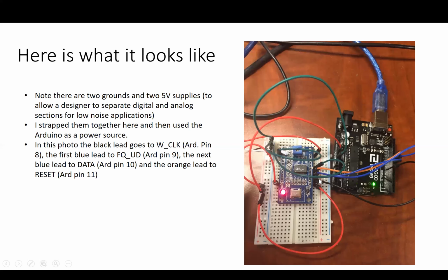What I have done is to push the AD9850 board into a breadboard. It's a little tough to do this. My pins were not exactly a 1/10 inch spacing, so be very careful when you do this. Once it's done, I suggest you just leave this board as the AD9850 board and don't take it in and out, because then you can just use these connectors here to connect easily and change connections to the board.